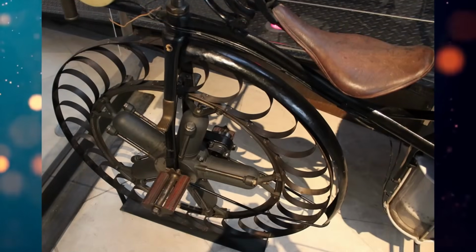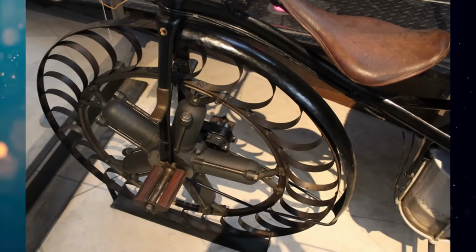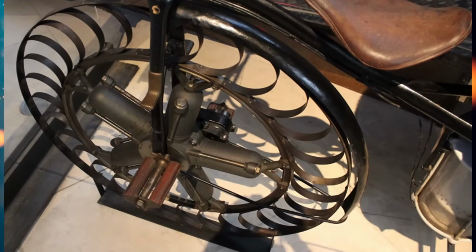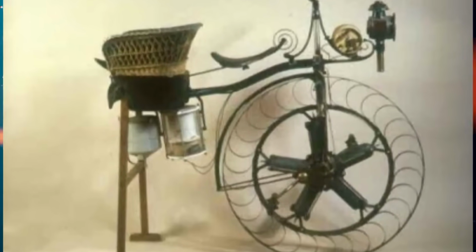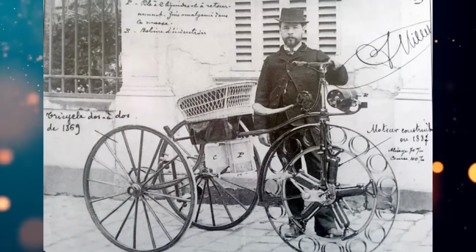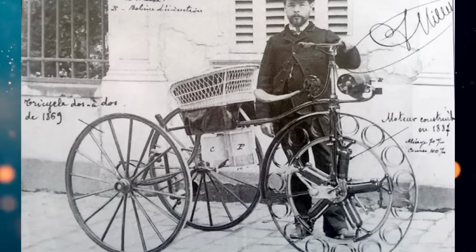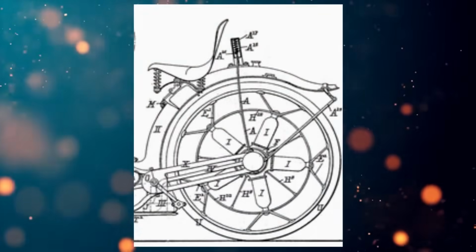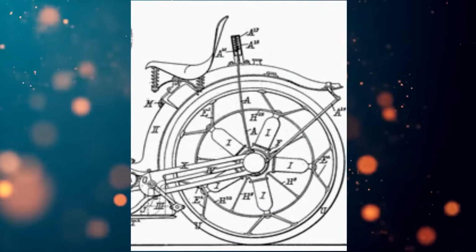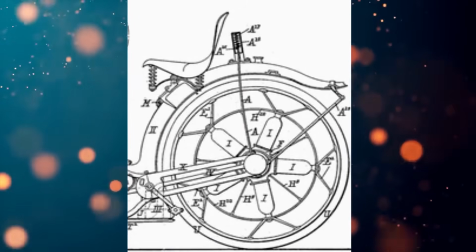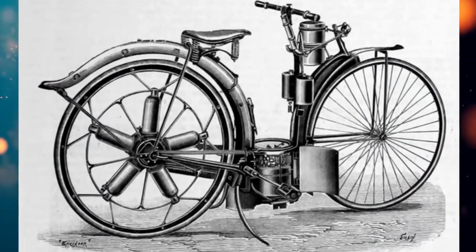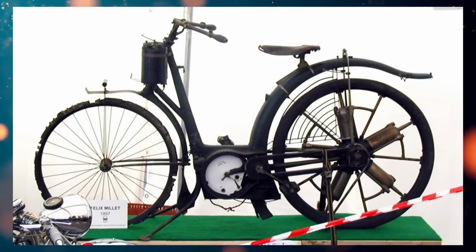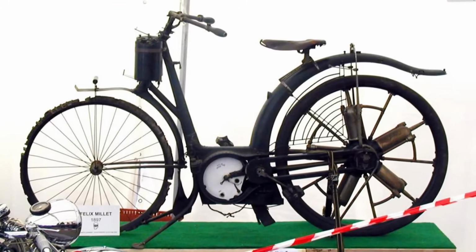In 1887, he invented a 5-cylinder rotary engine, patenting it a year later. In 1889, Mille installed it in a tricycle's front wheel. Such an engine is ideal for installation in a wheel. You fix the crankshaft to the fork or swing arm, so the wheel and engine rotate together. The problem with this installation option is providing power to the engine in the large gyroscopic moment of the motor wheel. In 1892, Mille installed this engine in the rear wheel of a bicycle, thus creating the first motorcycle in human history with a multi-cylinder engine.